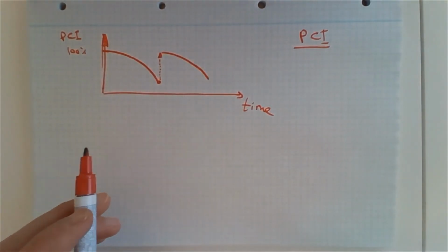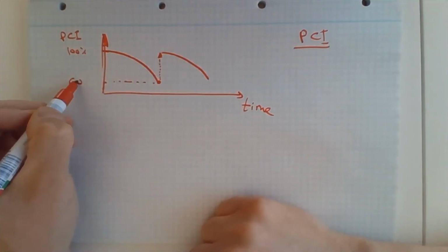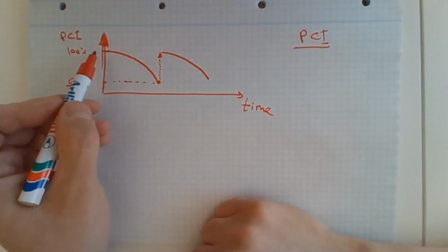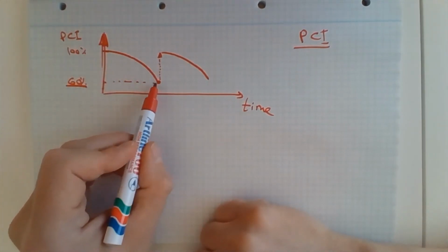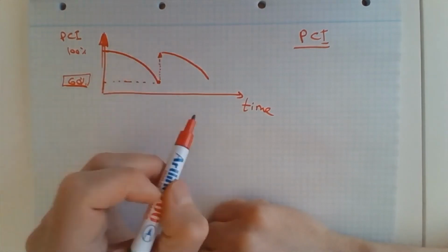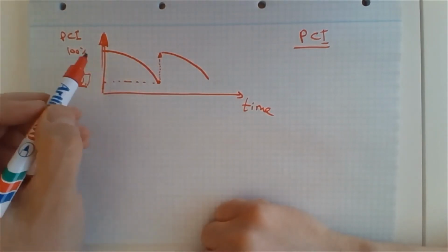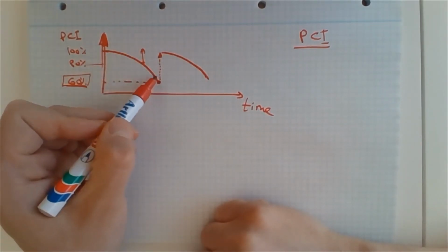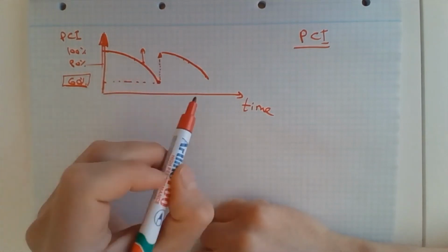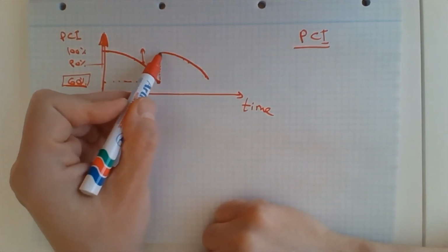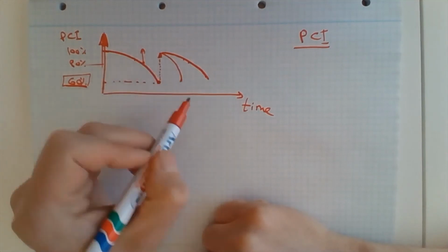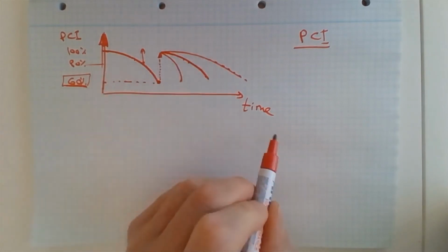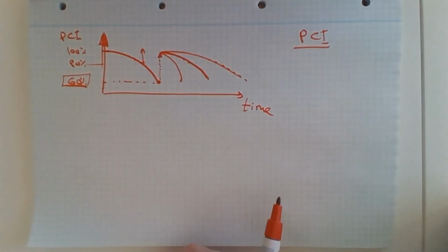So some interesting things to see here. First, the level at which we would like the pavement to be repaired is a decision. We can make a pavement management decision that whenever the pavement condition index drops below a certain threshold value, we have to repair. So this can be chosen to be here. It could also be chosen to be here. Secondly, after repair, we can observe the deterioration curve over time and check if the repair was done in high quality. If the deterioration curve is faster after the repair, that means the repair was not done in a good way. And if we have a prolonged deterioration afterwards, that means that we really targeted in the repair the causes of the problem.